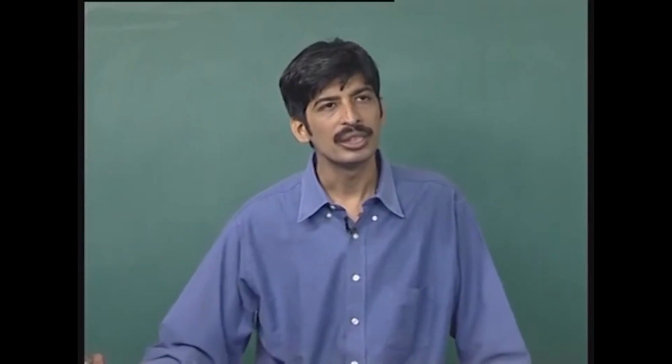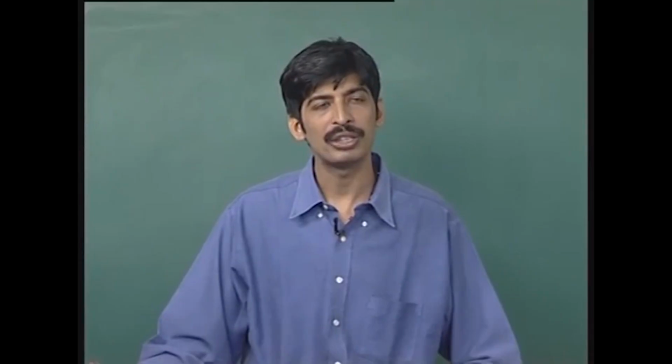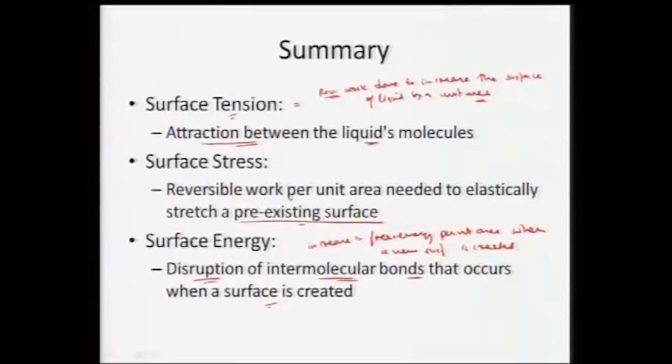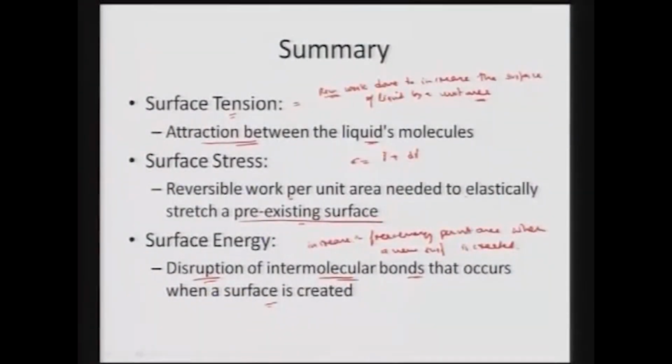Once we take a plane of 100, 111, 110, depending on the orientation of atoms out there, the stretching will be very different, and the surface energy of those regions will be very different. So we define solids via a term called surface stress, and that surface stress equals surface tension plus the change in the surface tension with respect to the change in the straining of the material.